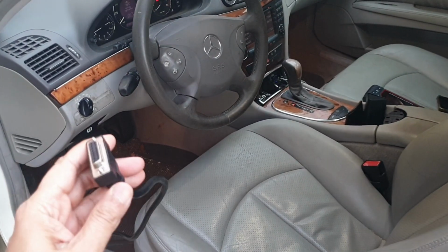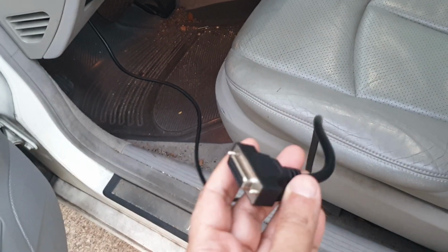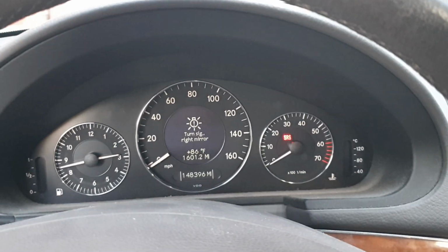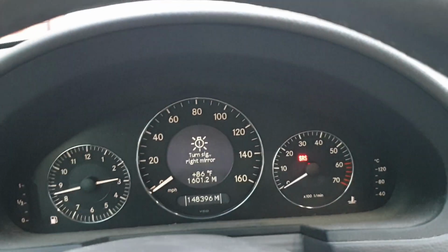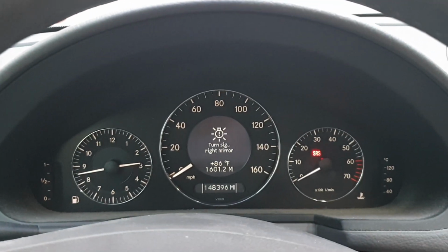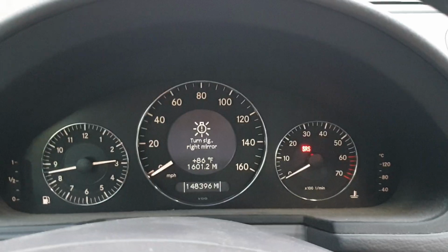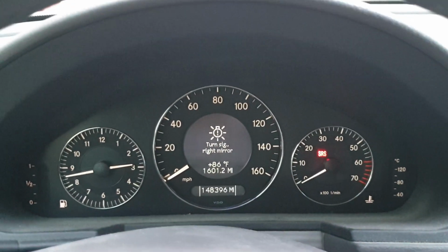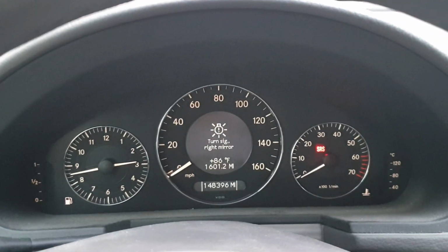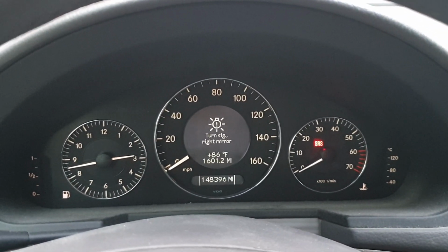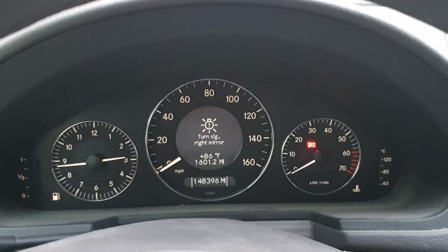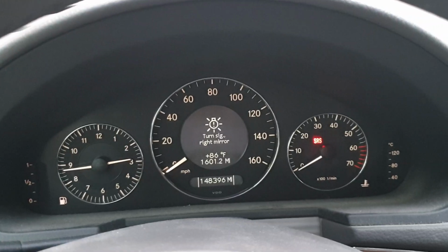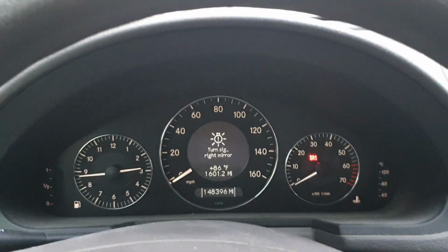Okay, so I'm going to be checking the live data with the OBD2 port. I'm getting two lean codes, P0171 and P0174, and I want to do some level of diagnosis to check the mass airflow sensor to see if it's working correctly, and also check the short-term and long-term fuel trims. I don't know exactly what to make of that data, but at least if I have the data, I can begin to look into it.